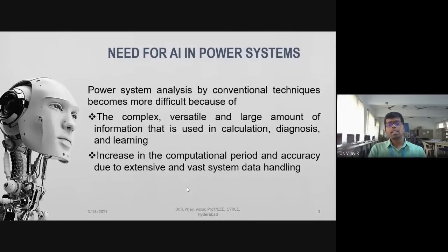Today's Tamil Nadu load is around 24,000 megawatt, but due to this summer it might change a little bit. About 500 megawatt is increasing today, because many of us are using ACs or ceiling fans. Today some 500 megawatt suddenly increased, so we have to forecast. Load forecasting is a very important problem in which the input is very large, and we are going to discuss it.